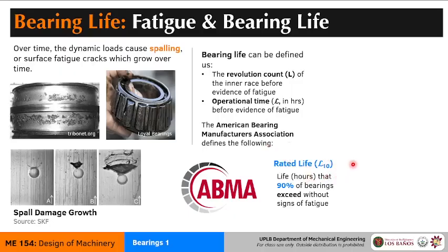The rated life of a particular model of bearing is the number of hours that bearings in one set can exceed, and not just exceed, 90% of those bearings have to exceed. So again, the rated life is the number of hours that 90% of a single batch of bearings can exceed.